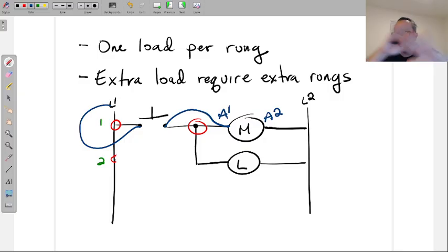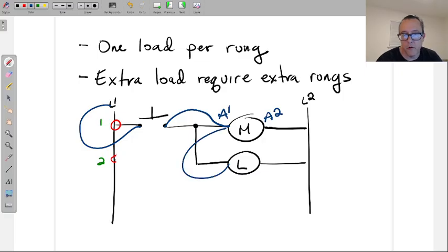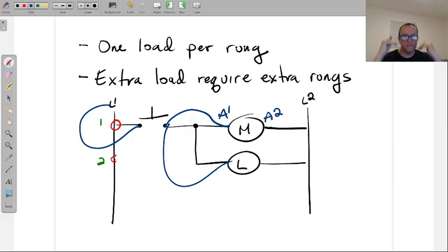All right, it can disconnect wires, stuff can start to shut off, and now you're creating secondary problems to the mix. So whenever you have a little dot in the middle, you're going to have to find a place to put that wire. So you can bring the wire to the motor starter, or you can bring the wire to the push button. All right, there's the diagram, and then there's how the person wired this. All right, I'm going to say that again so it can be absorbed. There's the diagram, the way it was written, and then there is the reality of what's going on in the field. How was this thing actually wired?